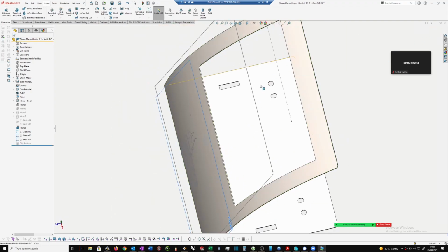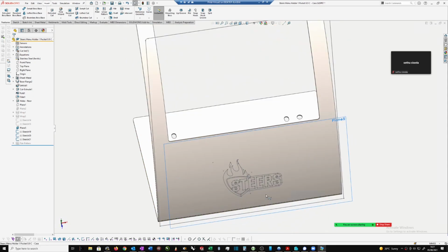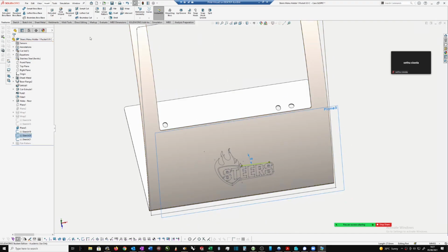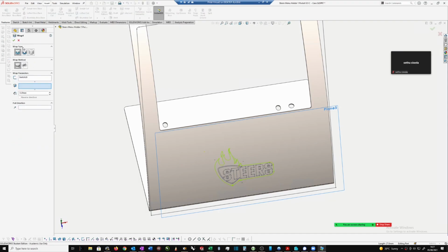The point about it being a block is that you can move it as a unit instead of moving the separate lines. So then once you've got those selected, you can select a sketch, and now you should be able to go and select to use this wrap command, and you'll see the wrap command has across the top 1, 2, 3 different options. One is to emboss, which means come out, deboss, which means go inwards, and then scribe, which just means create a line that you can use to then break this up into 2 different surfaces. So at the moment we want to deboss it.